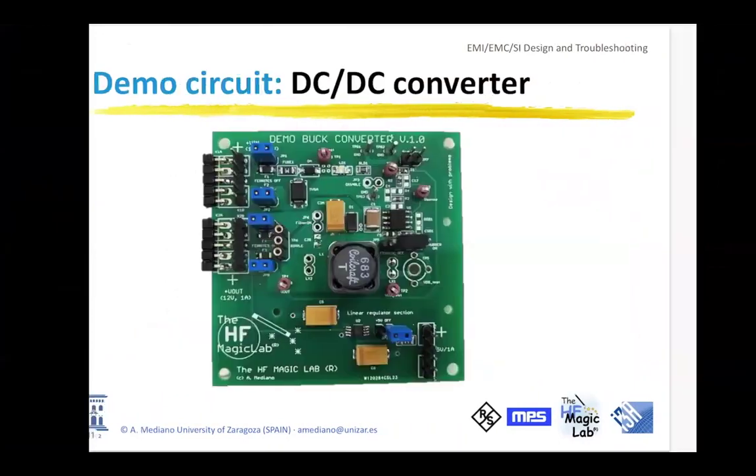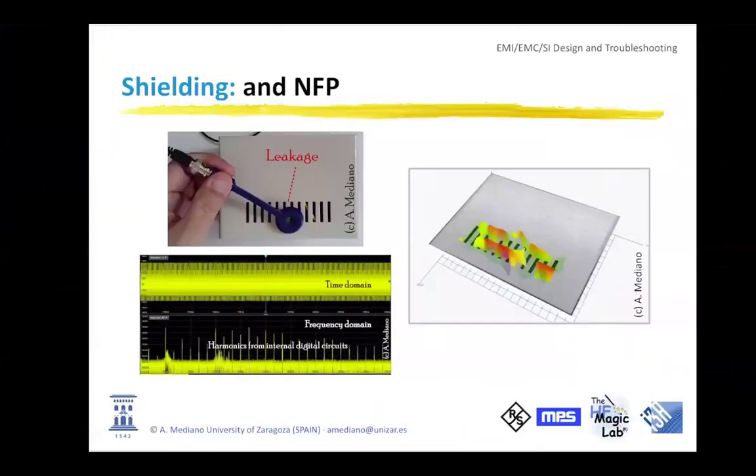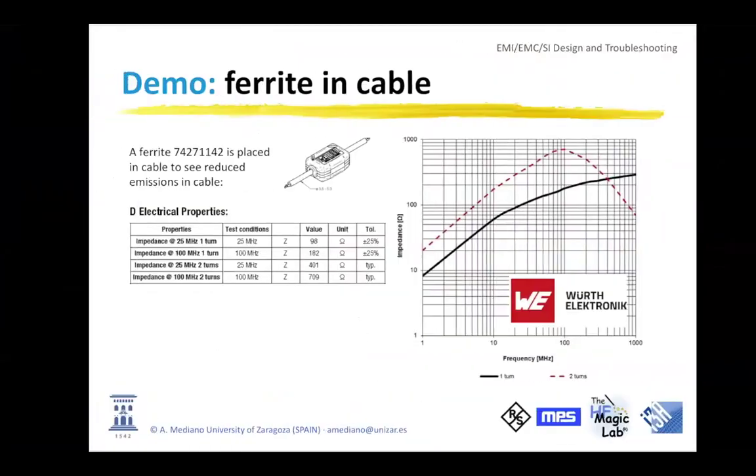Okay, so this is the ferrite I will be using. You go to a ferrite and try to find one that, in the frequency range of your interest, 100 to 1000 megahertz, has some specific impedance. If the impedance is in the area where it is maximum, this area is typically related to a resistive effect for the ferrite. That means you will be introducing a resistive effect, 800, 700, 600 ohms, and the noise will be dissipated.